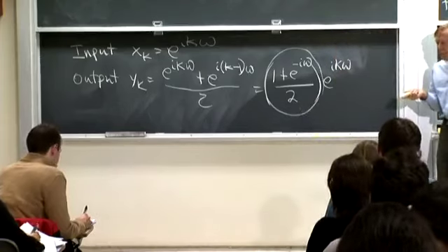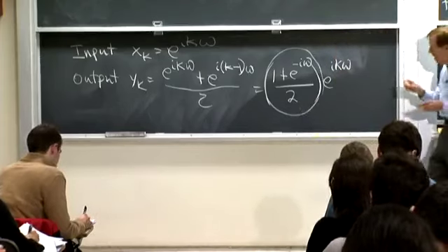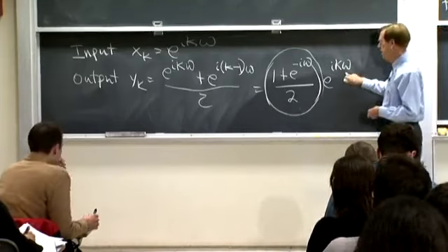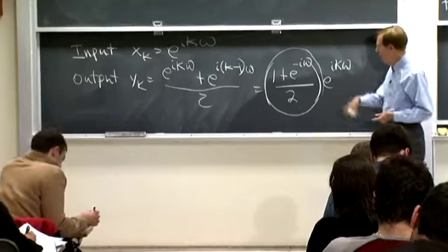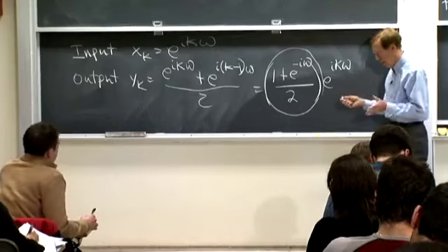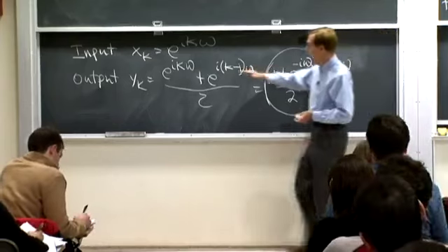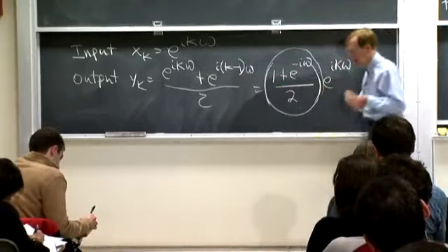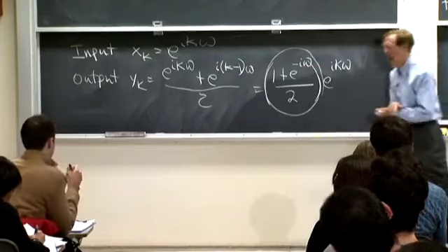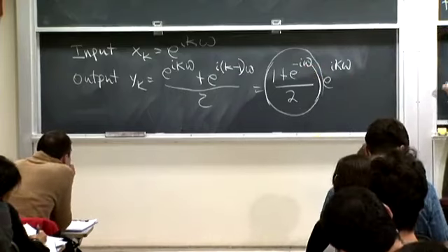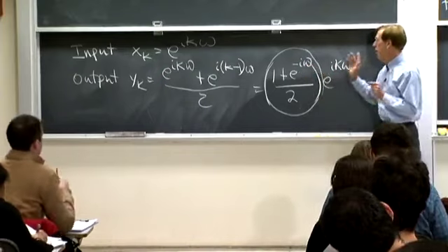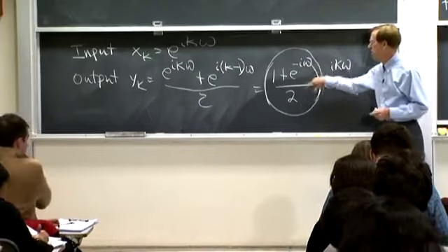the frequency response. So that's telling me the response of what the filter does to frequency omega. It multiplies the signal. If I have a signal that's purely with frequency omega, that signal is getting multiplied by that response factor, 1 plus e to the i omega. When omega is 1, when omega is 0, what is this quantity?